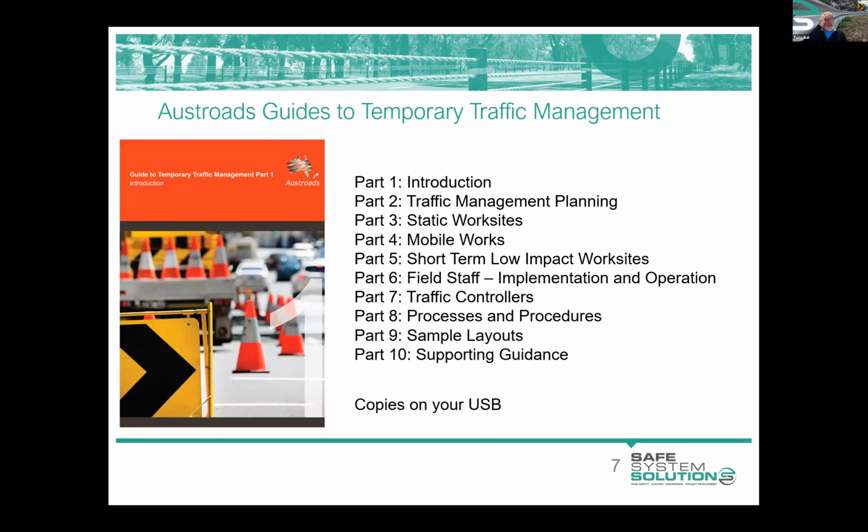So, while I mentioned that the compliance audit isn't a road safety audit, as a road safety auditor you need an understanding of what is required for management of traffic at roadworks. The new Austroads guides, although probably not so new now, were introduced at the end of 2019.